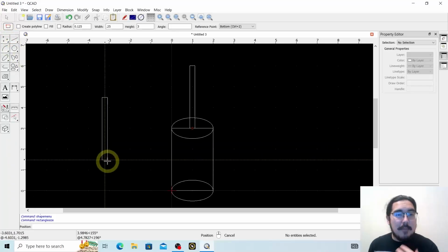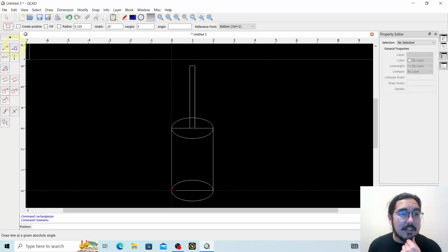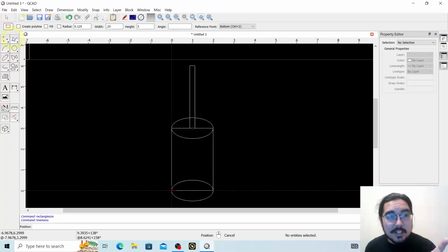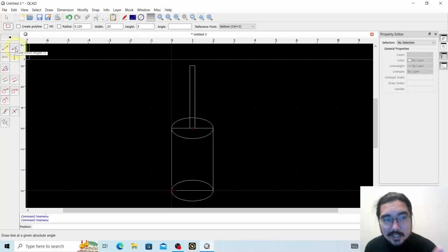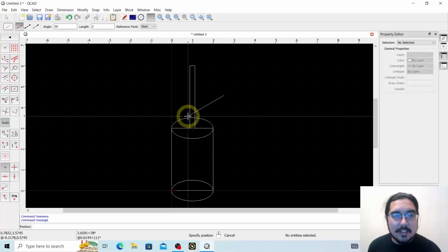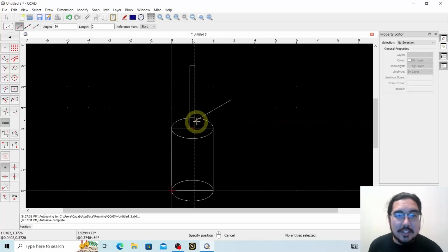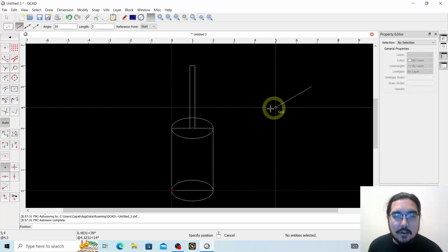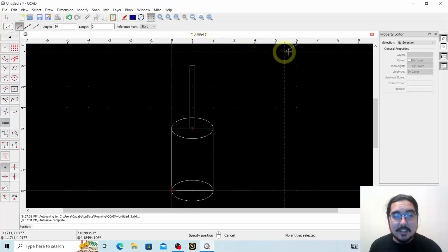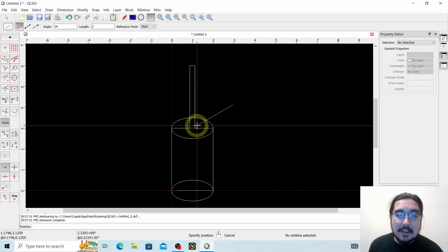We are going to make fins. Now they're not going to be 45-degree fins. That seems a little bit sharp of an angle for a lot of the designs that I've seen. So we're just going to go to our line from angle tool. Again, back to the main menu, go to the line tool, and then to the line from angle tool. And we're going to select a 30-degree angle. I like that angle there. And we're going to set a length of 2 inches. Now this is going to extend out and over the edge here. By the time we're all done, it's all going to be cut and squared together. But for right now, it's going to extend out over the edge.